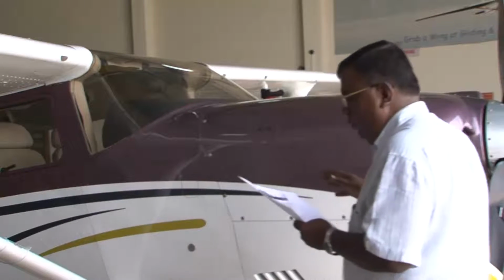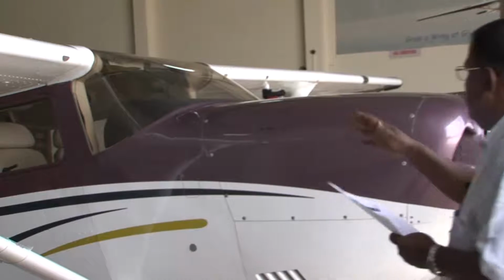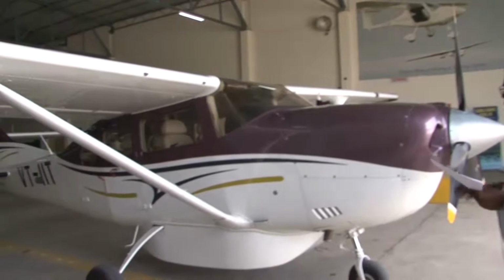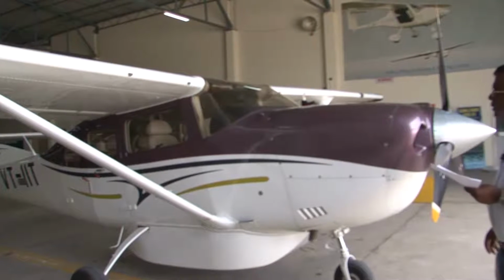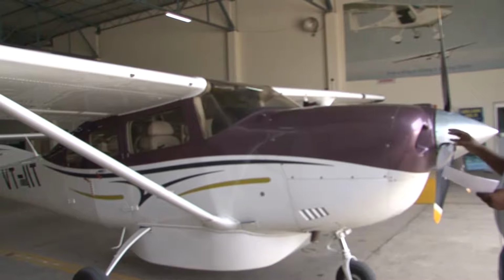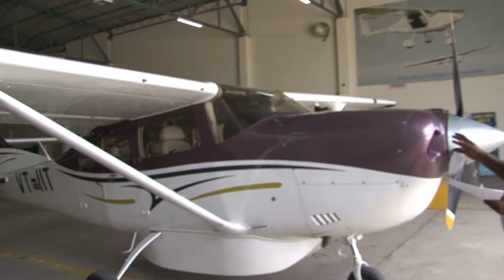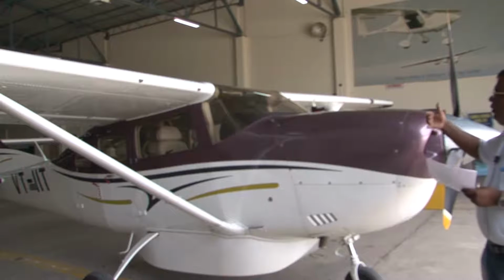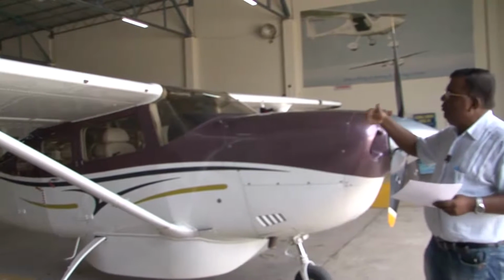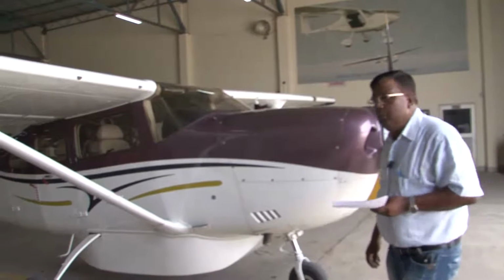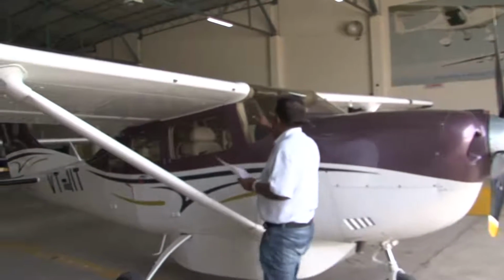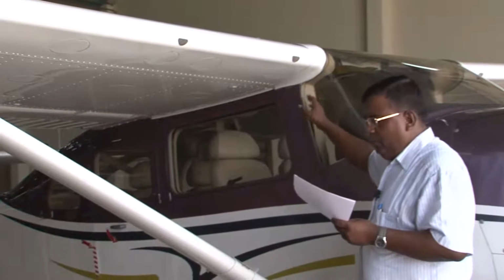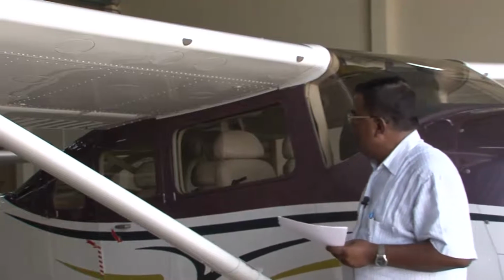So if you see the ratio, the total length is 28 feet 3 inches, and from here to the cockpit it is around 3 feet 9 inches. So the ratio is around 20 to 25%, 22% to be more precise. So when I am drawing a sketch, I know that I should keep this much percentage for the cockpit start point, and then depending upon passengers, I will lay out the dimensions. This is important for a high wing. For a conventional airplane, the high wing will start somewhere from here. So this is very important information for drawing a conceptual sketch.